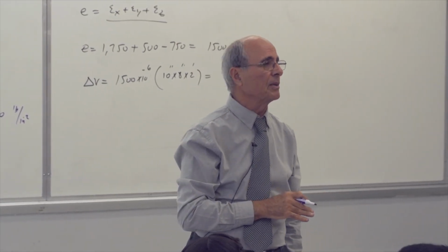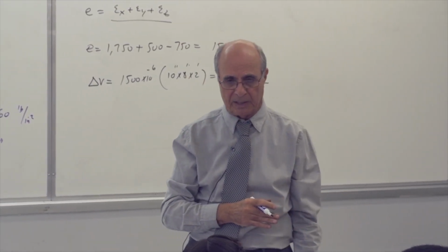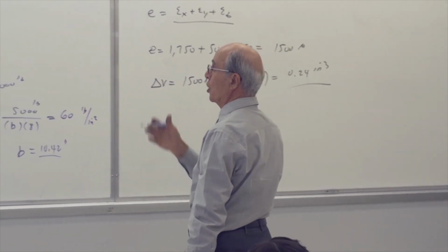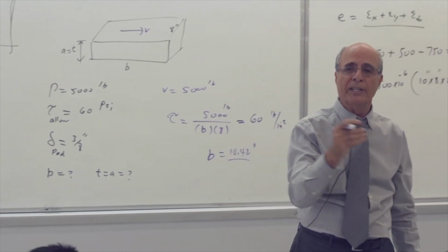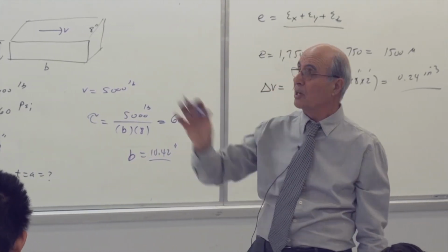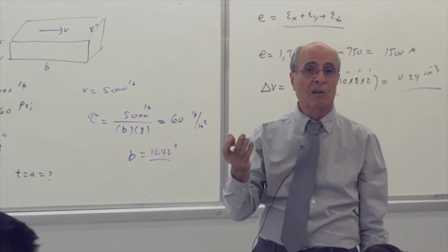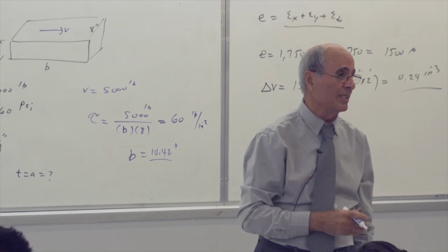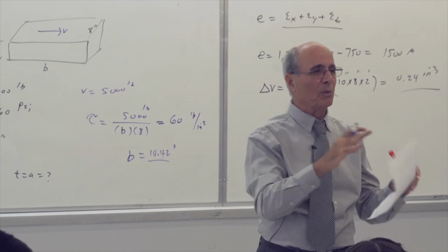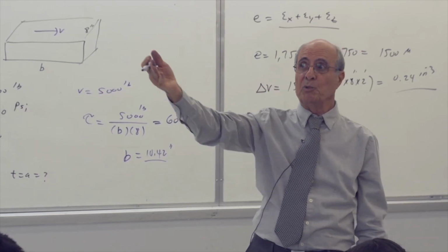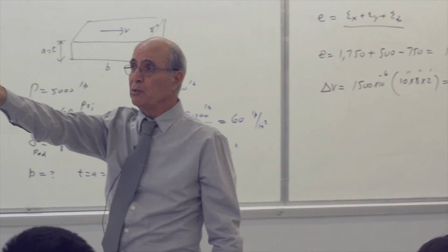Is that understood? But this is the flexible material, correct? That's why it can go more. Concrete cannot go that much. Concrete goes 0.01 inch. Remember, all the deformation we were calculating was less than 1/100 of an inch around that area. But this is a plastic material. It can go. That's why, by the way, between the glass and the steel there, you have a caulking.